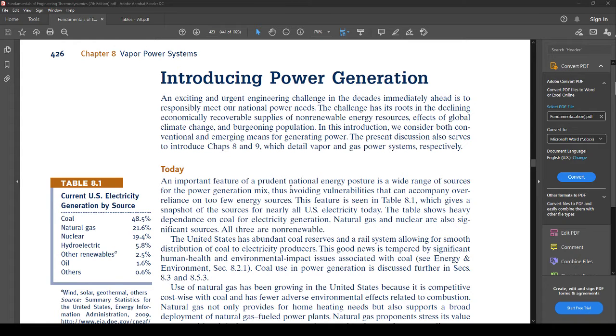I'm not going to go over too much of this, but essentially a vapor power cycle is more or less some working fluid heated up to a superheated vapor using the boiler, which is one of the terms I've been using the whole semester to try and bring us to here. It then gets expanded through a turbine. The turbine blades spin, which is attached to essentially the grid, right? This is how your power gets to your house after some transforming to make it home ready.